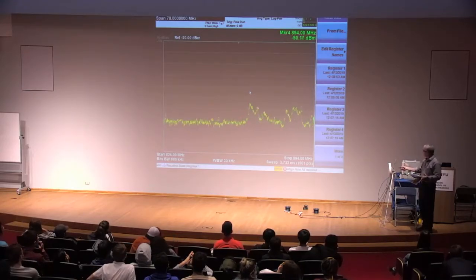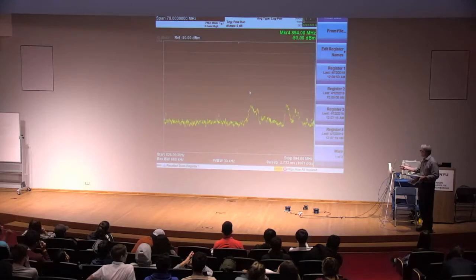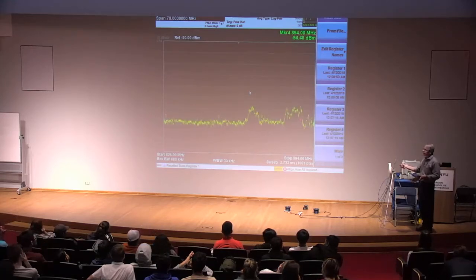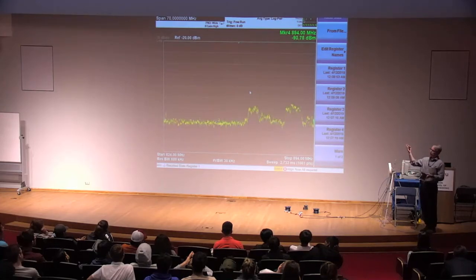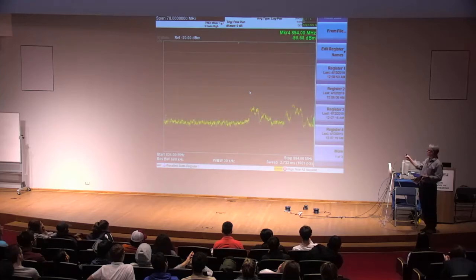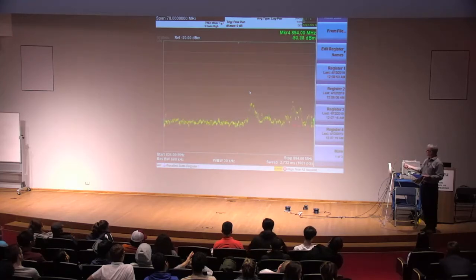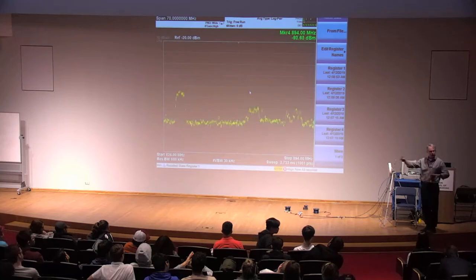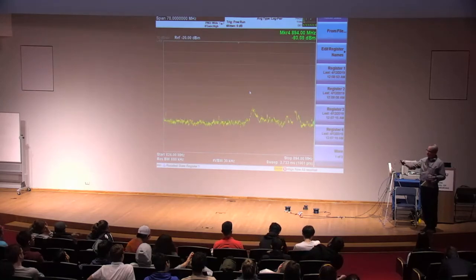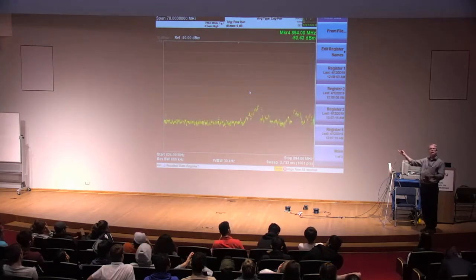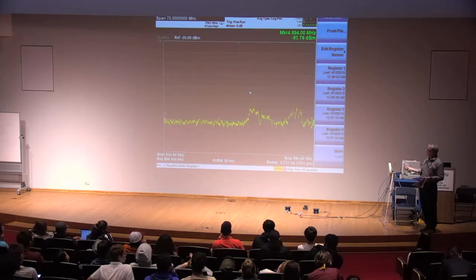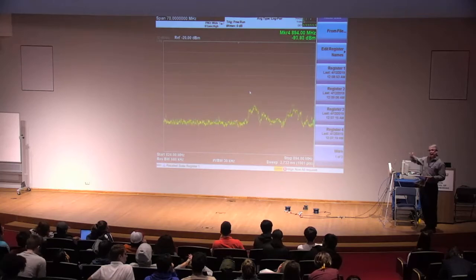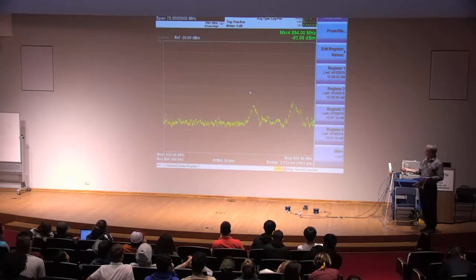And then the bands here, there's a marker here, 3 to 4. You see, this is on most of the time. This is the base station energy. So somewhere in this community, there are several base stations. We're near, probably, the closest one is what we're measuring. Base stations tend to transmit all the time because they're talking to many, many users, not just the ones in this room, but other users outside, out in the atrium and buildings around. So you see there's a lot more base station energy in the downlink.